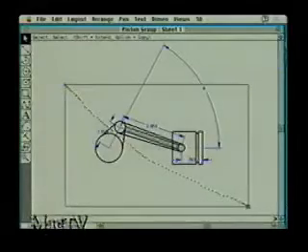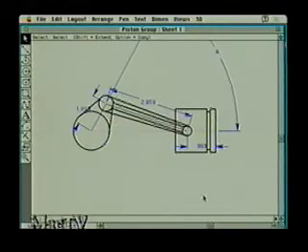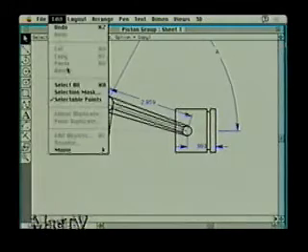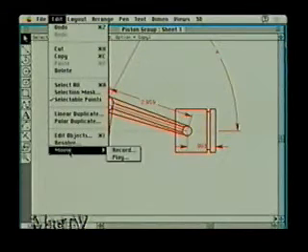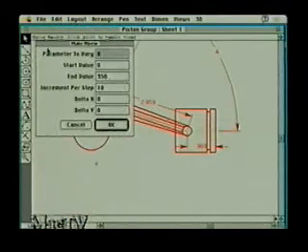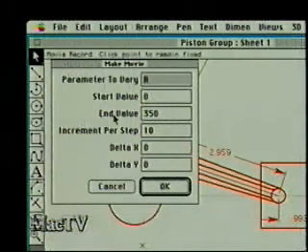Now I'm going to set up a viewing frame. I'm going to zoom in here with a command I call a stroke zoom, get a nice viewing frame. Then I'm going to select all, and then I'm going to do a movie, and I'm going to record this movie. What I do is I tell it I want to take that variable A, start at 0, end at 350, and go in steps of 10 degrees. So do a resolve at 10, one at 20, one at 30, all the way around the circle to 360 degrees. And I won't have any changes here.